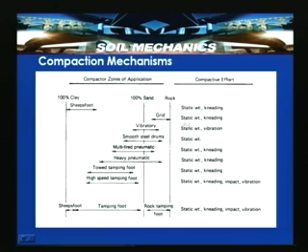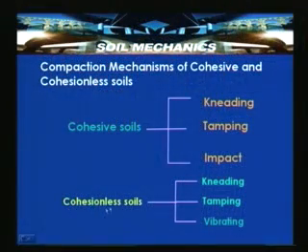The compactive effort, if you look into it, is static weight, kneading, and impact vibration. Sometimes the static weight will not help, so vibration, along with static weight, is required for compacting coarse grained soils. As we have discussed, cohesionless soils can be compacted by kneading, tamping and vibrating, and cohesive soils by kneading, tamping and impact vibration.